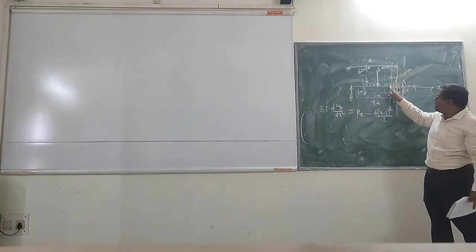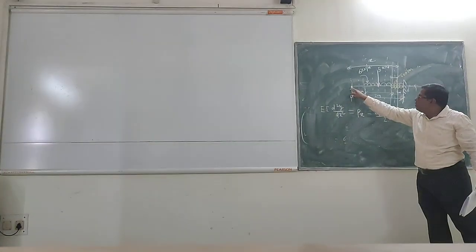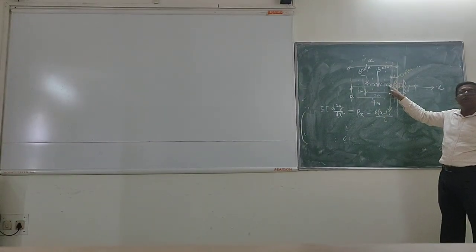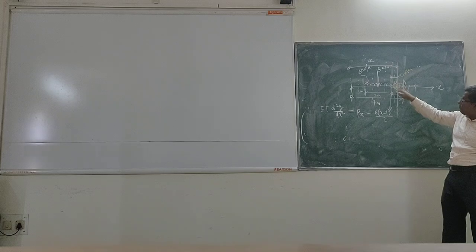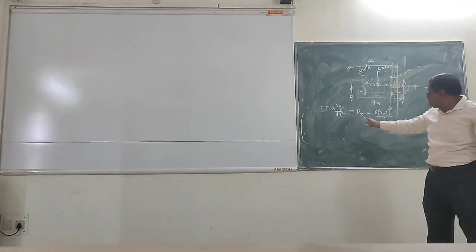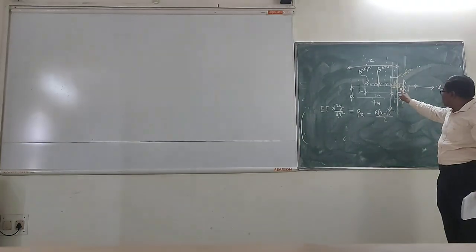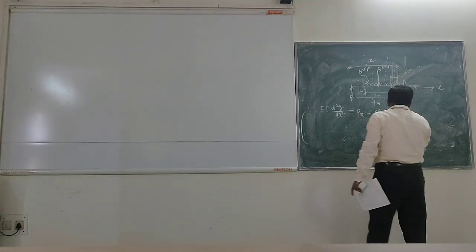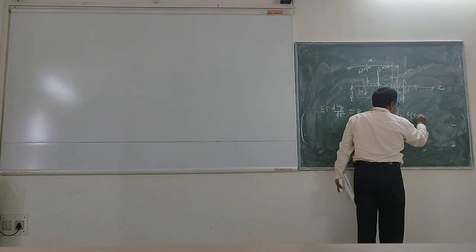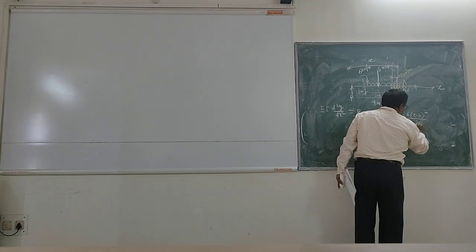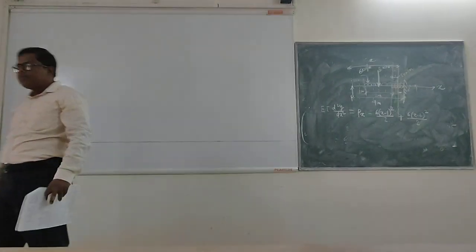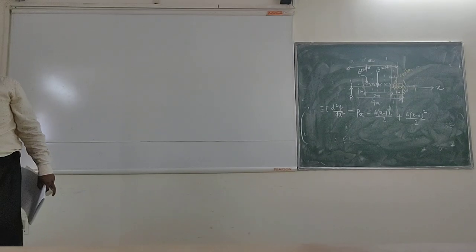So that is 3 meters, and it is applied in the reverse direction. So the moment will be positive, and this load gives plus 6 into X minus 3 whole square by 2. Have you understood why it is X minus 3 whole square by 2? Is it clear to everyone?